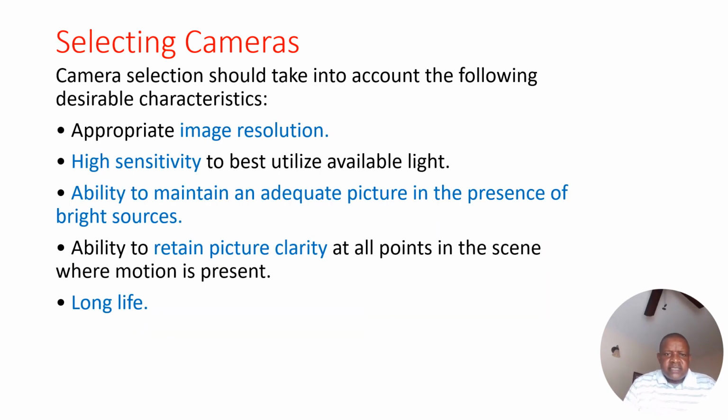Also, selecting cameras. When you are selecting cameras, for example, you are a security manager, you are a security supervisor, and you are sitting in a forum where you need to select cameras, these are some of the considerations you need to take into account. You need to consider appropriate image resolution. What type of resolution do you need? High sensitivity to best utilize available light.